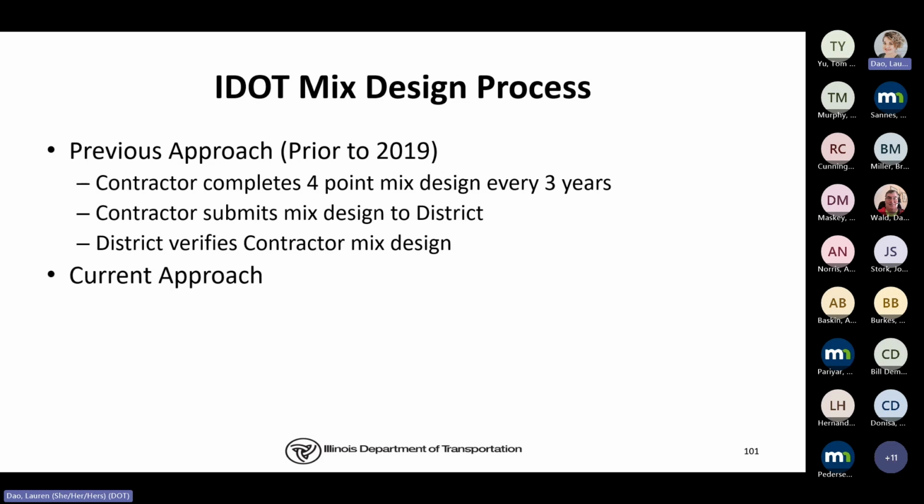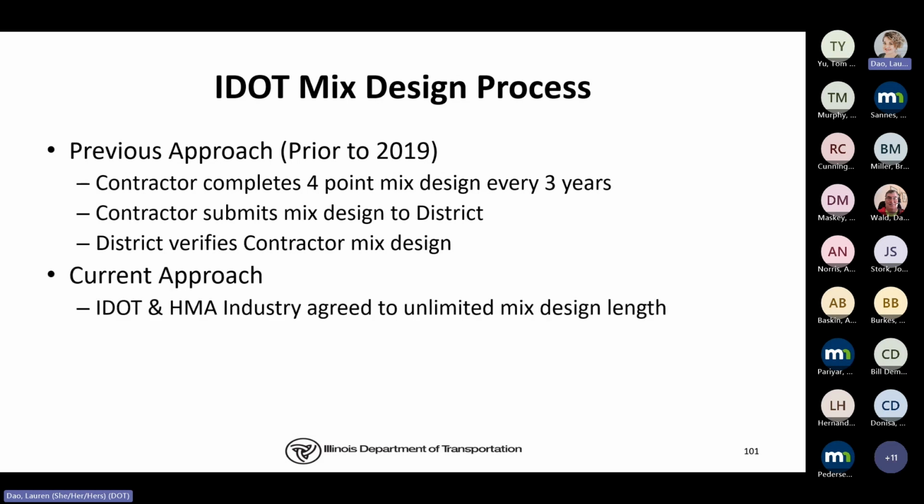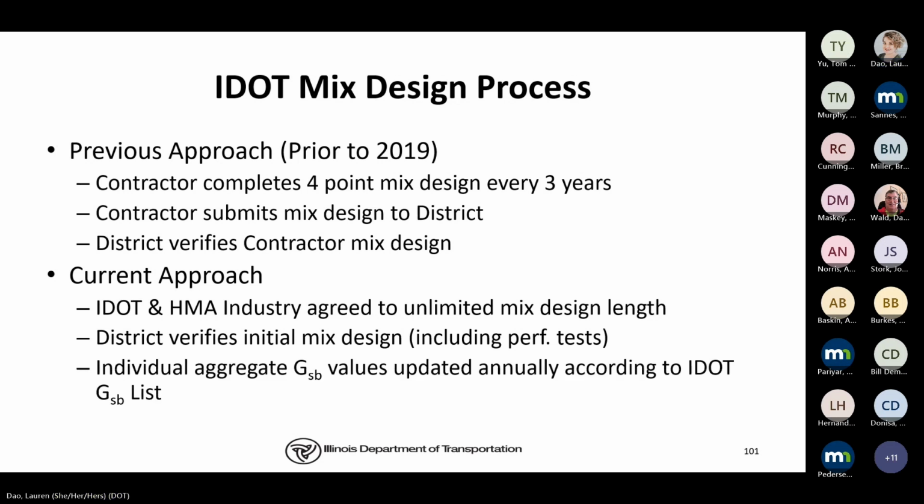Now, in our current approach, IDOT and the HMA industry allow unlimited mix design length with some additional caveats. The district verifies the initial mix design, including performance tests, and we update the GSB values annually based on the IDOT GSB list.